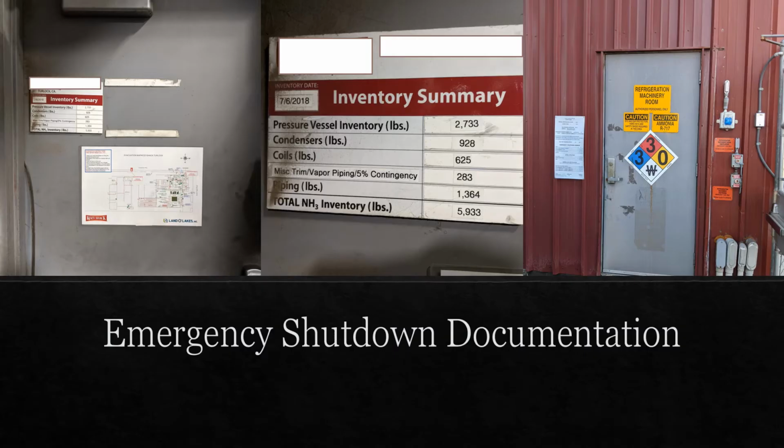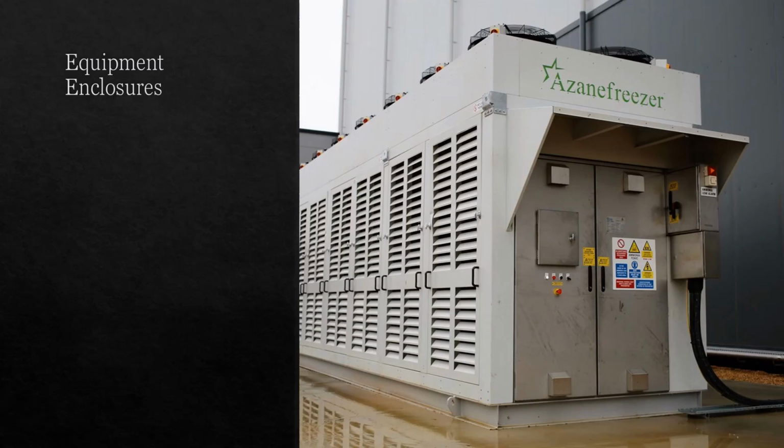Section 7.2.10 states that it is the duty of the person in charge of the premises to provide directions for emergency shutdown that are readily available. This information must include details and steps for shutting down the system in an emergency, names and telephone numbers for operating and maintenance staff, names and numbers of government agencies that must be notified of a release, quantity of ammonia in the system, and emergency facility contact information.